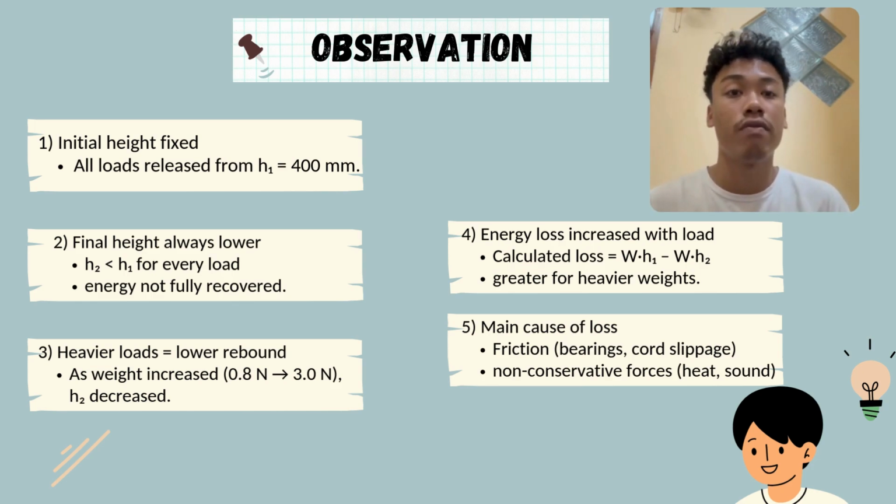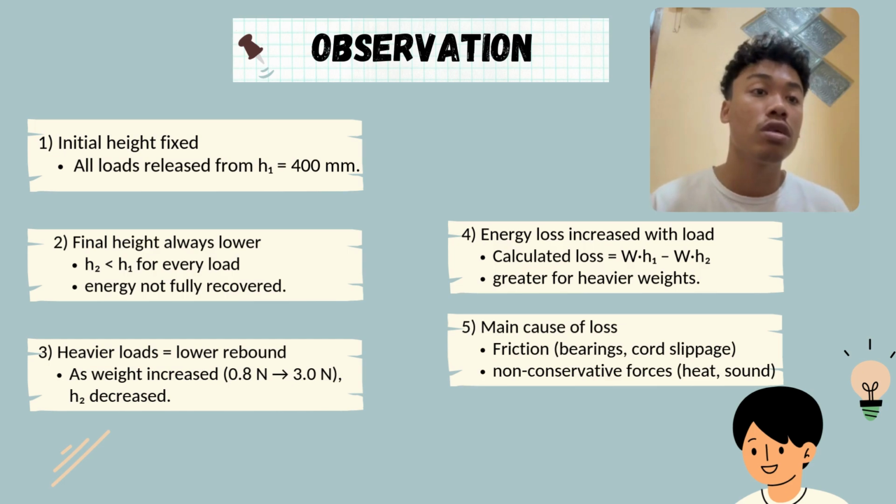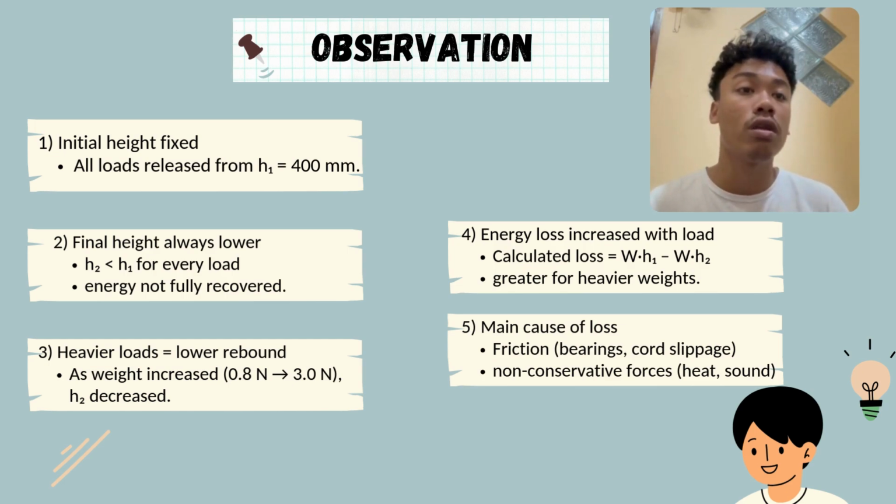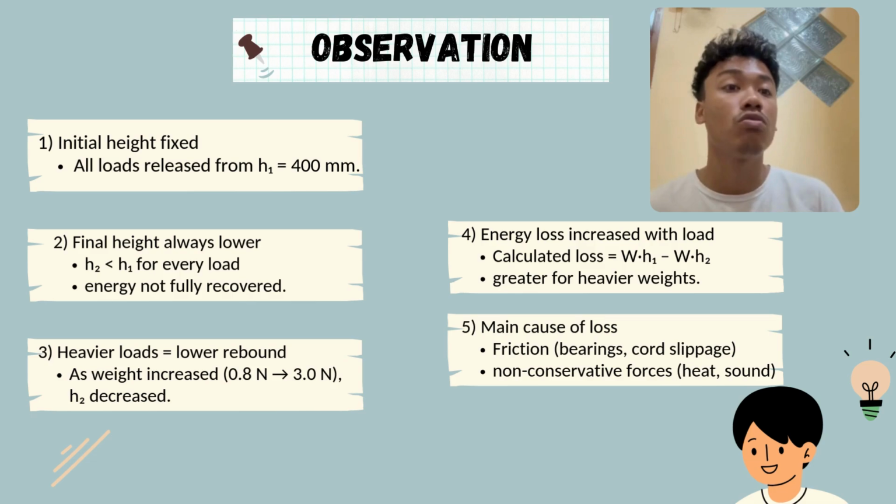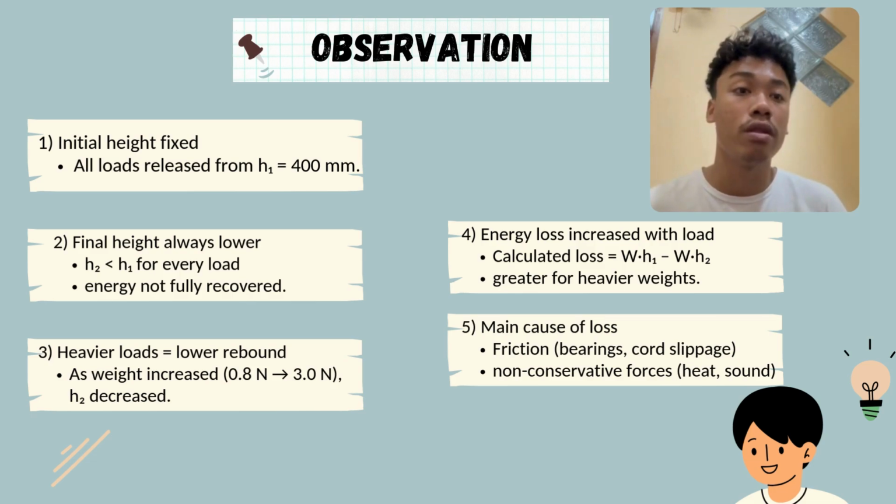Energy is not fully recovered. Third is heavier load equals lower rebound. As weight increases from 0.8 Newton to 3.0 Newton, H2 decreases. Fourth is energy loss increases with load. The calculated loss, W·H1 minus W·H2, is greater for heavier weight.